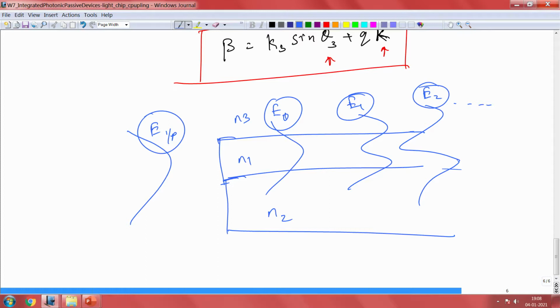As we have seen in many coupled equation or light coupling problems, when you have non-zero overlaps, you have potential coupling. That means exciting one particular mode is not straightforward. If you can couple to the 0th order mode here, you may also be coupling to the first order and second order modes here, because they are even. So, the mode overlap will result in a non-zero overlap integral. It is impossible to avoid those.